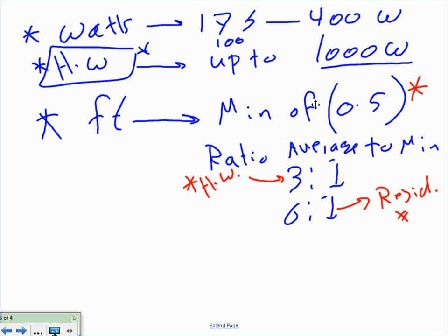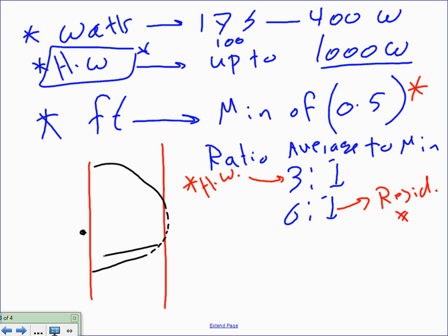And the last thing, if you look, when we were doing a parking lot, you have an isofoot candle that you can do. So if I put my fixture right in here, it will show the isofoot candle that this fixture is going to be covering. And if I need another fixture right here, the isofoot candle of this fixture will overlap, like we did with the parking lot. Remember how we did the parking lot? You put your fixtures to overlap.